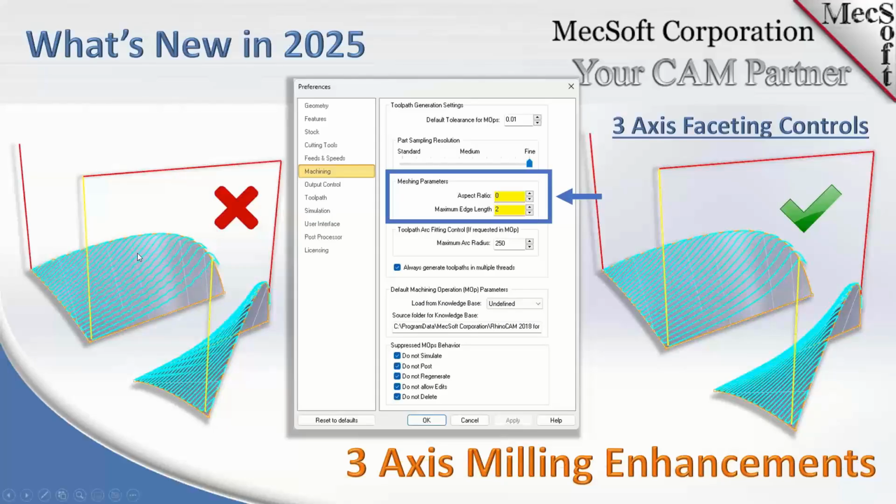And these typically don't happen all the time. It's a very small percentage of cases, but it can be pretty annoying if, in the middle of your large part that has hundreds of surfaces, you have one surface that gives you behavior like this. So this has been annoying to some of our customers who are doing sophisticated work. What we have done to improve that is to give users more control to set the initial meshing parameters to get the toolpath computation started.